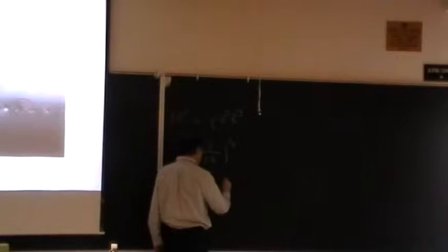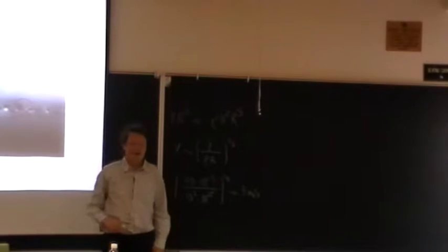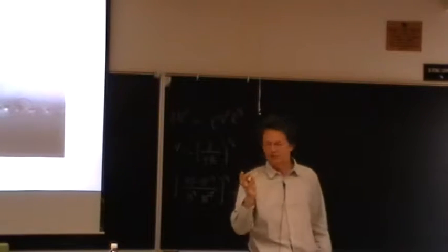And numbers are very interesting there. Surface tension of water is 70 times 10 to the minus 3. Rho is 10 to the 3. And the radius here is 10 to the minus 5, remember, 10 micrometers. And so you get something which is square root of 7. Fortunately, we calculated yesterday square root of 7. It's something like 3 meters per second. And so this ejection takes place at a velocity which is half of that. So really the order of magnitude is correct.